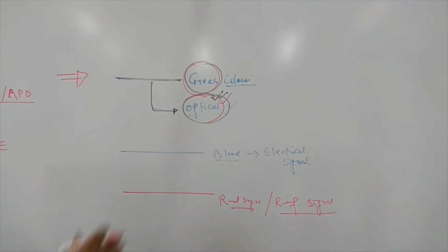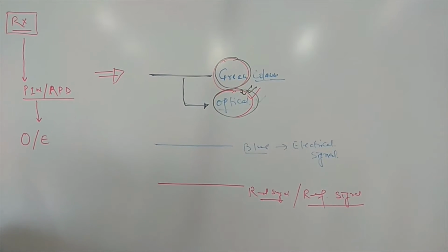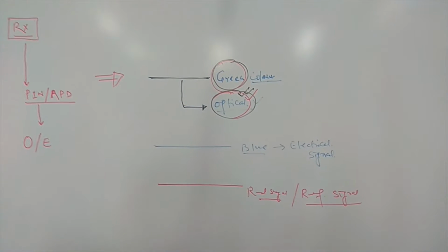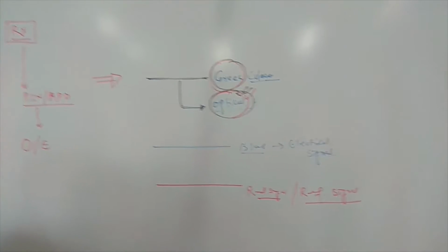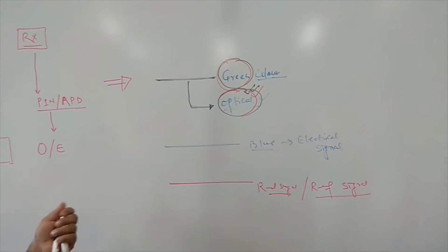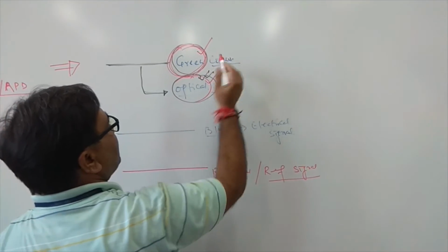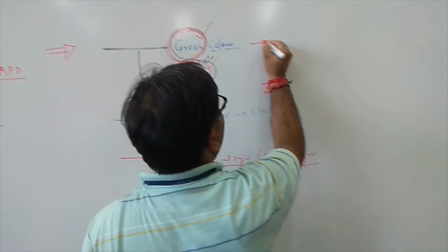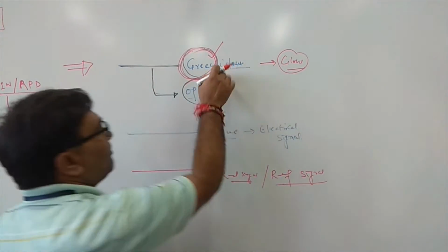In the last class I gave some theoretical concepts, and this is the practical concept: as an engineer, how you can identify on which side a fault has appeared. If the green signal is not glowing, there should be a channel problem.